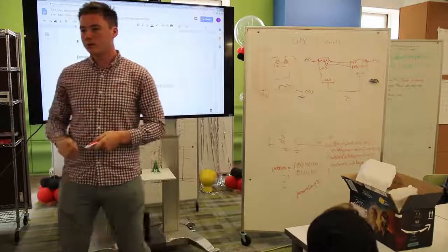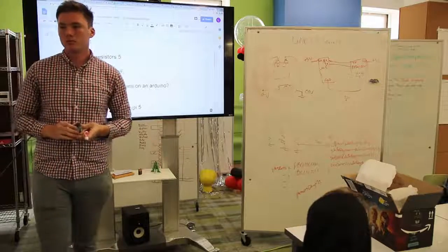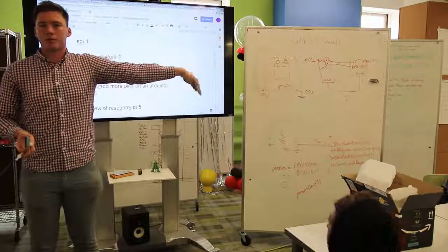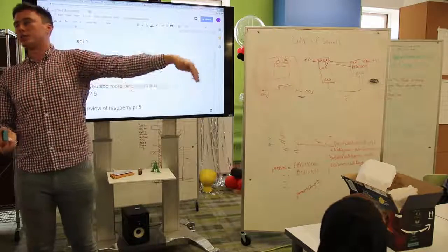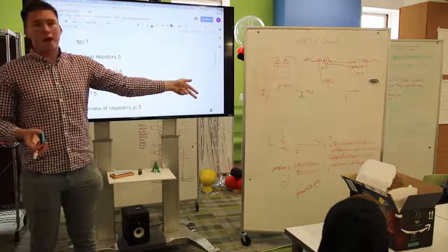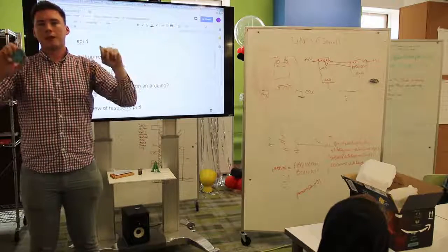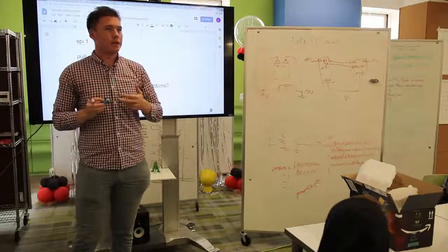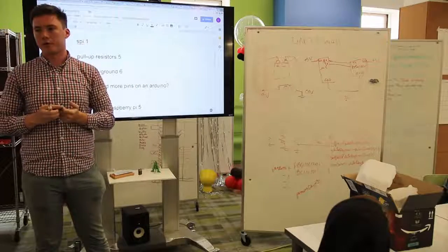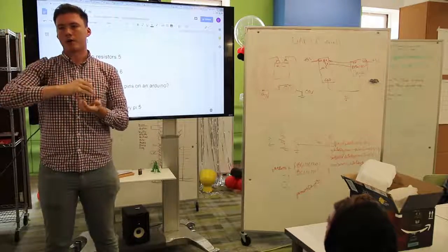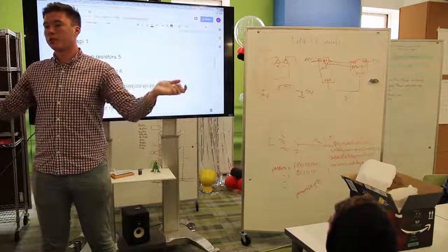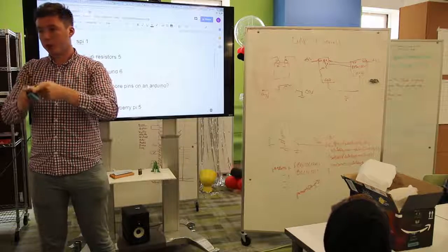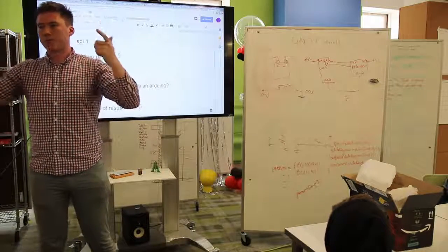Cool. So I don't understand why they wouldn't be able to function without the grounds being connected? Why they wouldn't be able to function without the grounds? Remember when I said this node is 1337 volts and this one's 1328 volts? It's sort of like that, where they're working from their own ground, and their ground is defined relative to themselves. So my plus 5 volts is relative to my ground, and your plus 5 volts is relative to your ground. Those grounds could be wildly different, but as soon as you connect them by a wire, they're instantly exactly the same potential. So anything greater than that is working from the same reference. Does that make sense? Yeah.